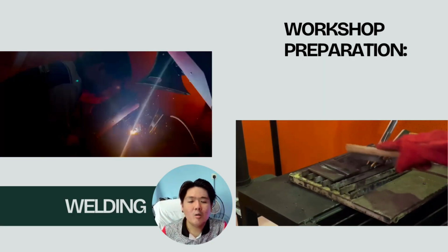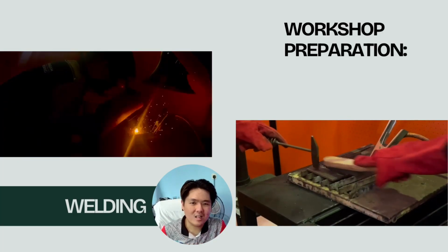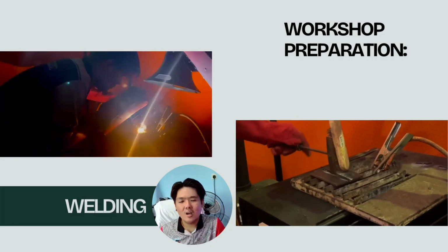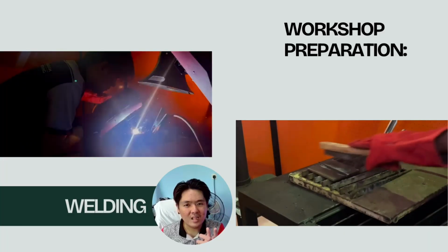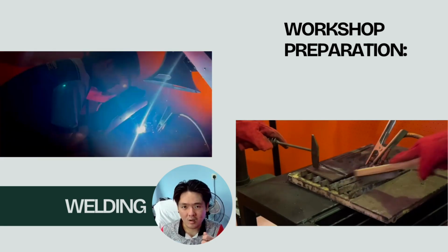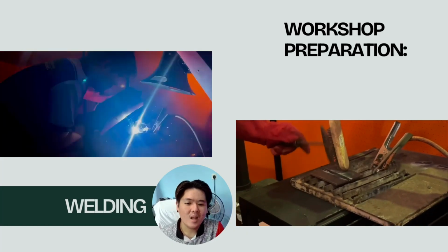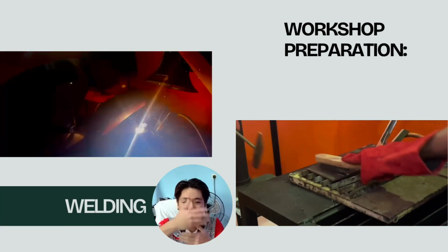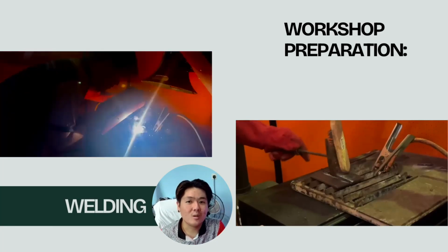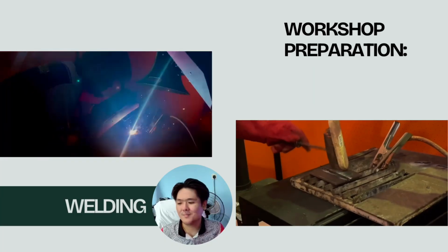The welding machine is also checked to ensure proper cable connection, electrode condition, and correct polarity. What intrigues me the most is the electrode condition. We call it the filler material, like a stick. We also checked whether the shielding gas is sufficient to prevent welding defects. And lastly, safety equipment such as the welding helmet with the visor, the gloves, and also the apron must be worn to protect the welder. Because, as you know, the high melting point might burn your skin too.